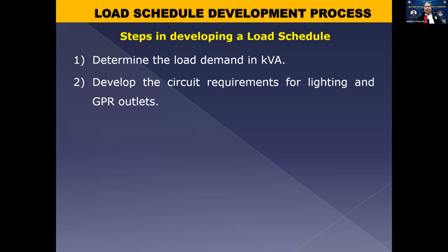These are devices that are numerous in a system and spread out in various areas, with no specific assignment. So we have many lights in the living room, dining room, etc. Same also with the outlets. That is why we should first develop their circuit requirements: how many circuits, and how many of these fixtures in a circuit. We have best practices for that, and we also have code provision limitations for outlets in a particular circuit, okay?